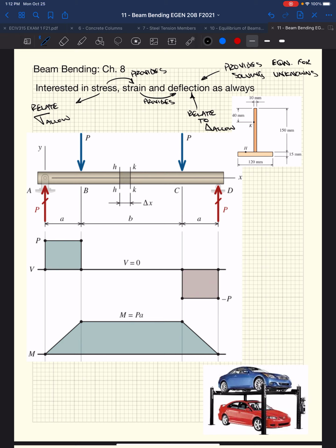As we've talked about in this class, there's strength requirements. We want to make sure stuff is strong enough, but we also want to make sure that it doesn't deflect too much, right? Serviceability becomes an issue. We want to make sure that it's actually usable. And we talked about if this floor vibrated too much, it would become unusable, right? Like I couldn't be teaching here because someone's kicking their leg over there and it's vibrating this whole floor, right? So we can't have that.